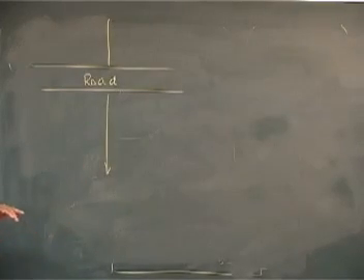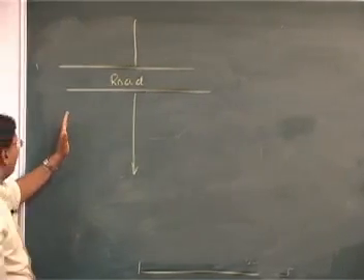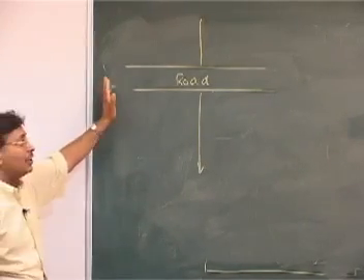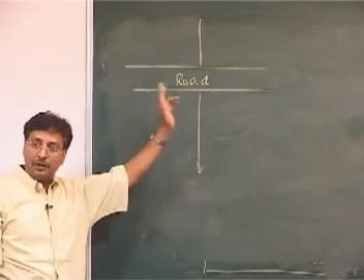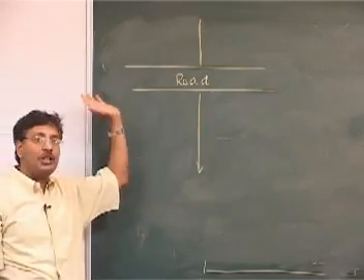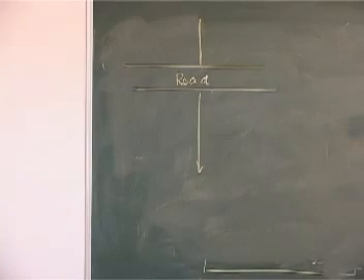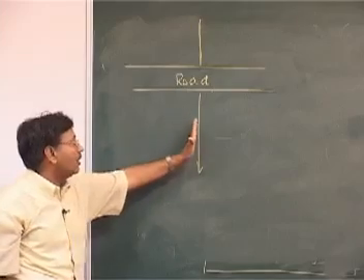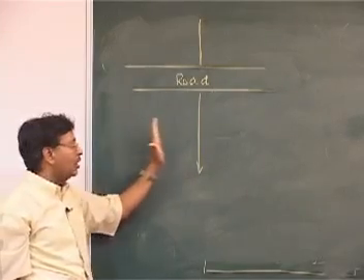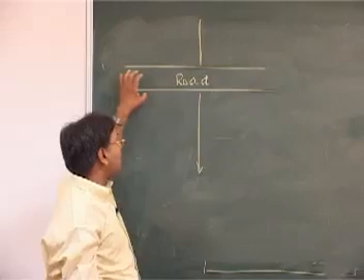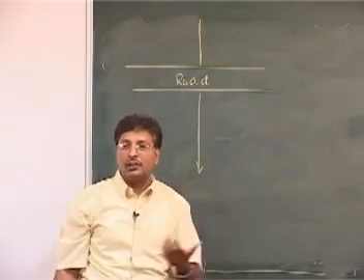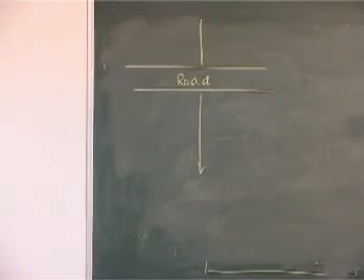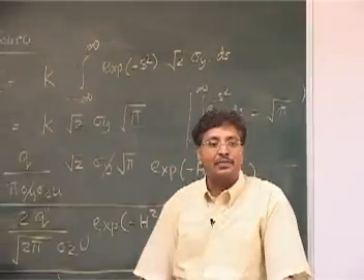Wind is blowing like this, okay, and your y term has also disappeared. This is one thing we have assumed: we have integrated from minus infinity to plus infinity, so we have taken this line to be infinitely long. So what happens in this case is that when I change the y, your emission is the same all throughout. Is your concentration any more a function of y? It is not a function of y. So that's why your y has completely disappeared from here.